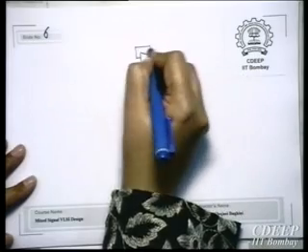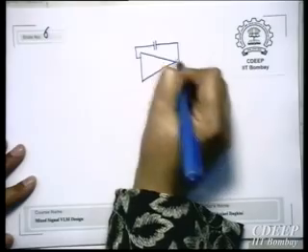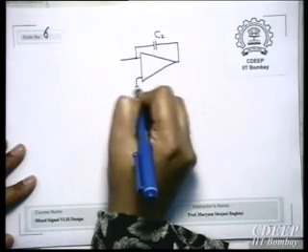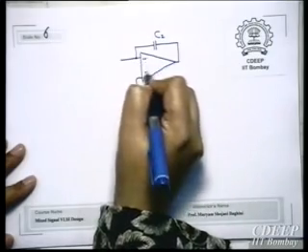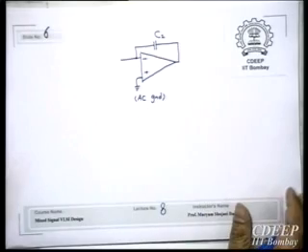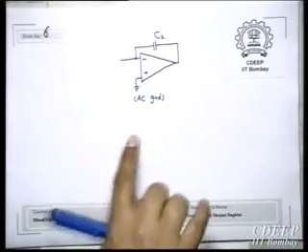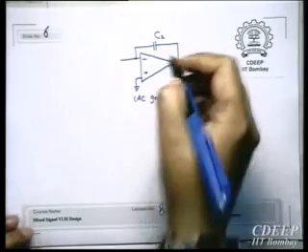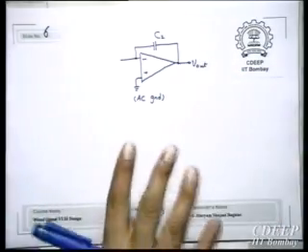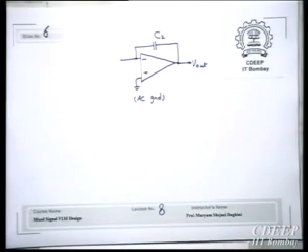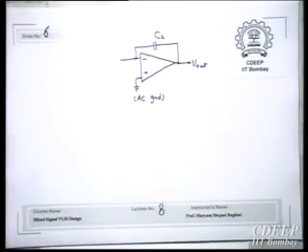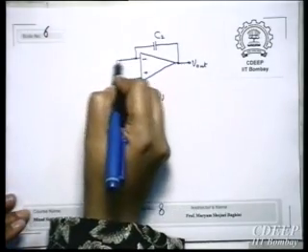These are very interesting circuits. See, notice whatever ground I show is AC ground. When you want to simulate and use a real op-amp, then it will be a reference voltage. Okay, so this is the output part. Always this output part is constant because that is the integration part. What we want now is to make this charge which is coming here to be the average of the input signal. Therefore, this is the arrangement.